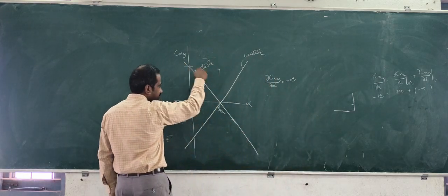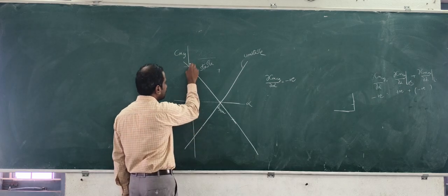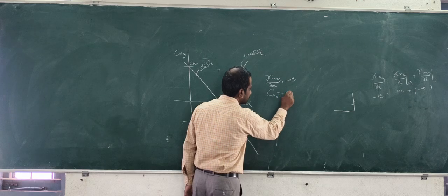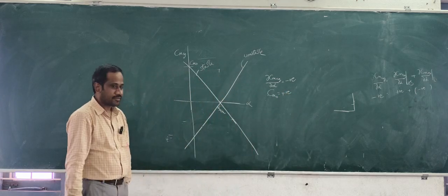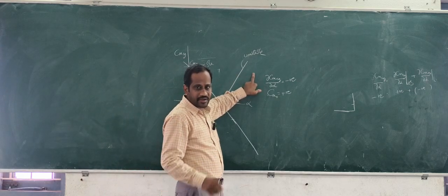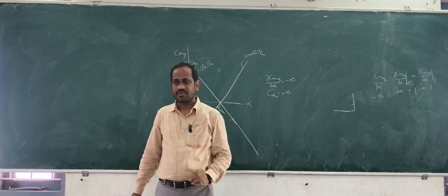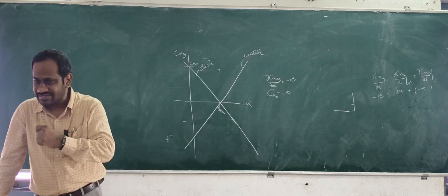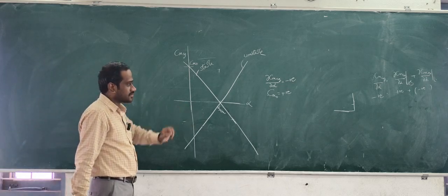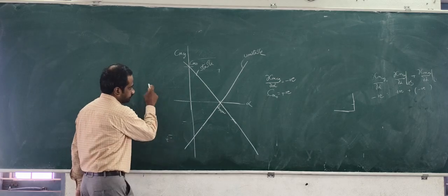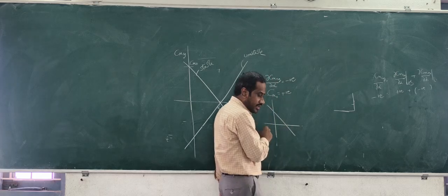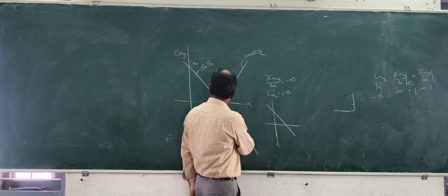So CM naught, I will talk about this. In the same vein, when alpha equals 0, this value is called CM naught. So CM naught is positive. These two things we laid under longitudinal static stability criteria. But truly, does CM naught positive represent a stability criterion? That's the discussion I make. Supposing, look at this. I make another diagram. So stability criteria, same graph.